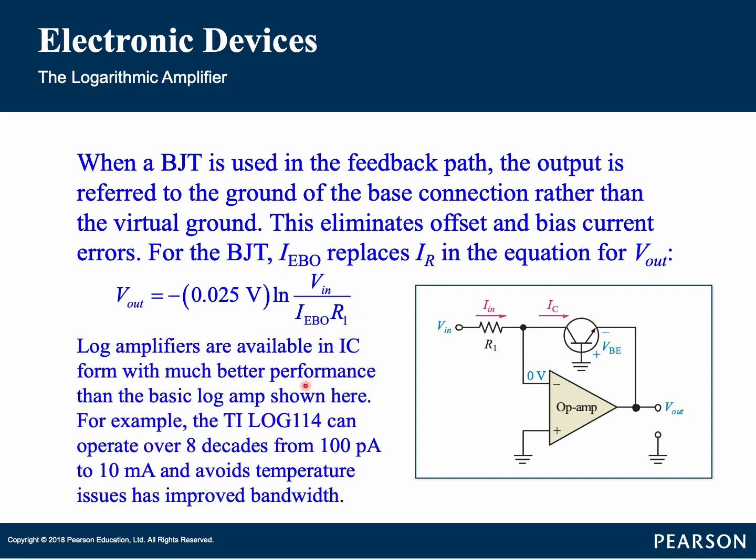Log amplifiers are available in IC form with much better performance than the basic log amp shown here. For example, a TI LOG114 can operate over 8 decades from 100 picoampere to 10 milliampere and avoid temperature issues, and has improved bandwidth compared to others.